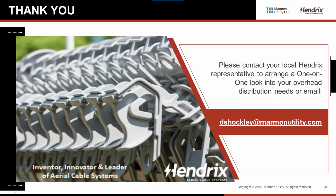The thing with polyethylene is it has a relatively high melt temperature. So you don't see a big spot where it's going to melt and burn back, like what you'd see with underground cable. We don't have a lot of voltage stress there, and there's not a ground nearby that's going to cause a lot of arcing over a longer period of time and a big glob of hot molten aluminum and everything melting together. It's going to be a relatively small spot. So it can be difficult to find, but like I said, fortunately it just really doesn't happen very often.